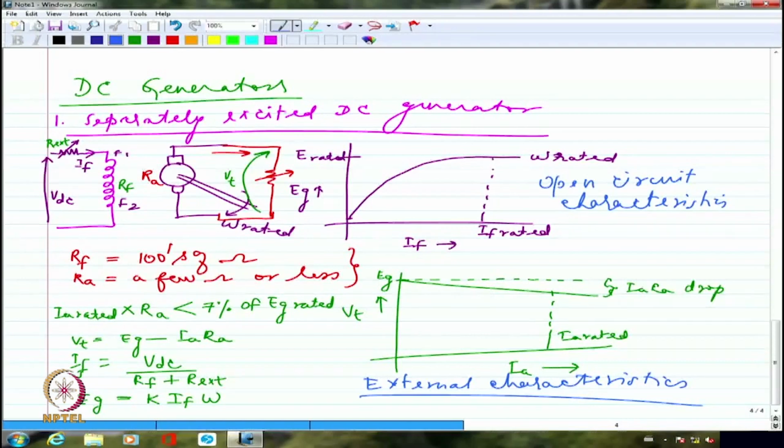We have to look at the reaction of the overall flux to the armature flux. The net effect of armature reaction would be to reduce the flux to a certain extent. But there may be some saturation involved, there may be some other crossover involved, because of which it is not a linear reduction as the armature current is increased.